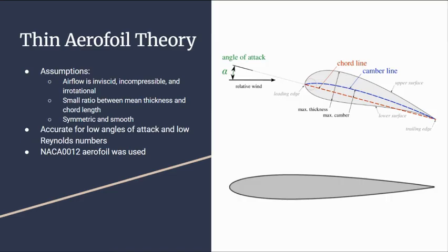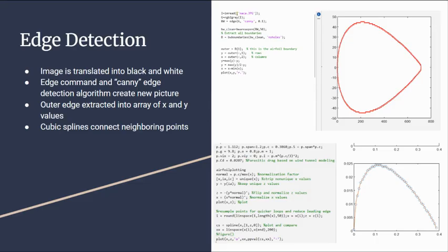Lift and drag can now be distilled into equations based on four factors: the 2D cross-section of the airfoil, the airfoil's total surface area, the density of the air around the airfoil, and the air velocity attacking the airfoil. With these assumptions in mind, the first major task is building the aerodynamic model, beginning with a cross-section of the airfoil in the x and z axes.